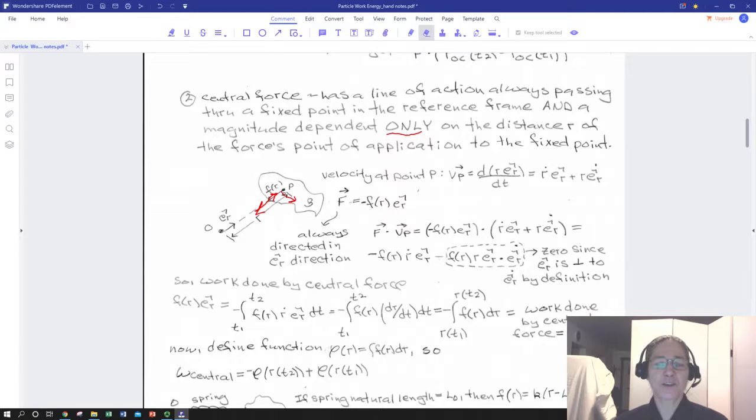This is akin to a two-force member in statics, where you can have a compressive load or a tensile load, but if you know the orientation of a straight member, you know the direction of the force. So in this case, that direction could be changing with time. It is dynamics, but you know it's always along a line between those two points.